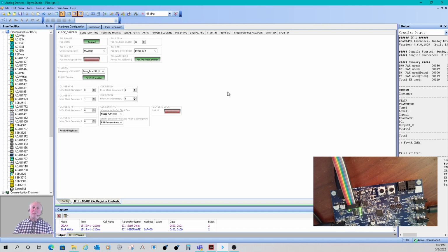And guess what? You'll have a sample rate that's half the rate. So that has to be correct as well. The first clock control page is obviously pretty important. This DSP has a main PLL that drives the whole system, and you have to set it up properly. You cannot run this DSP faster without it.